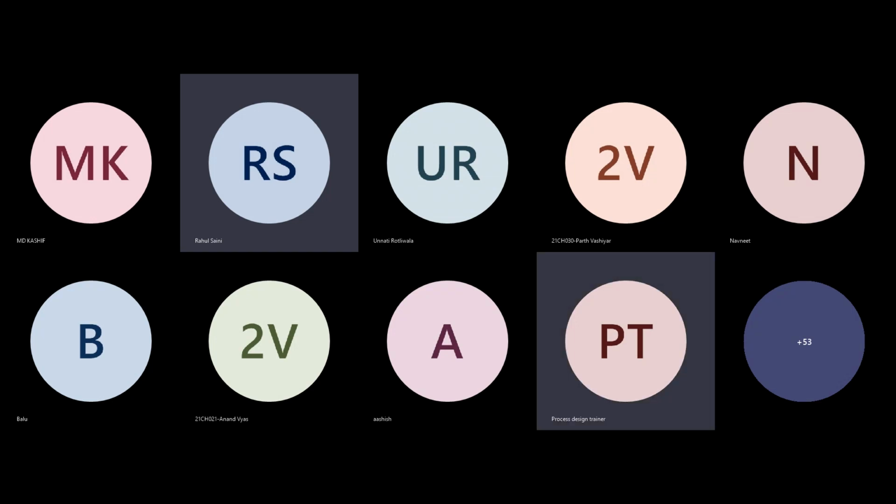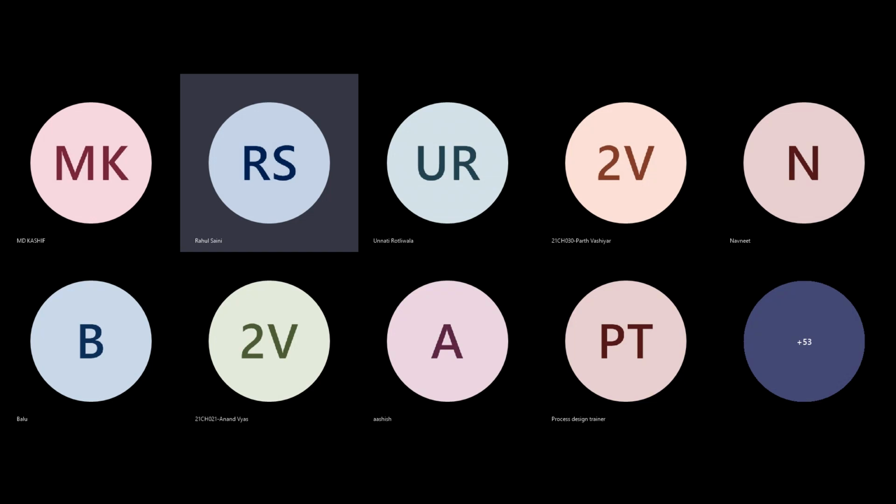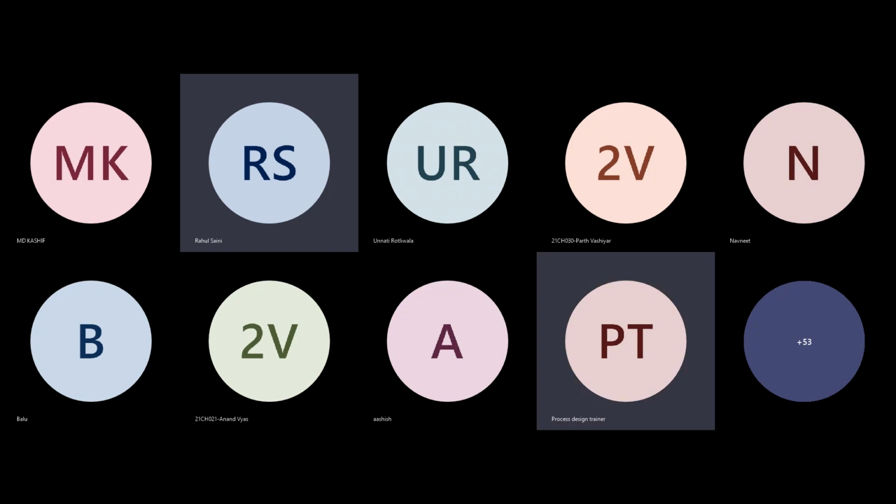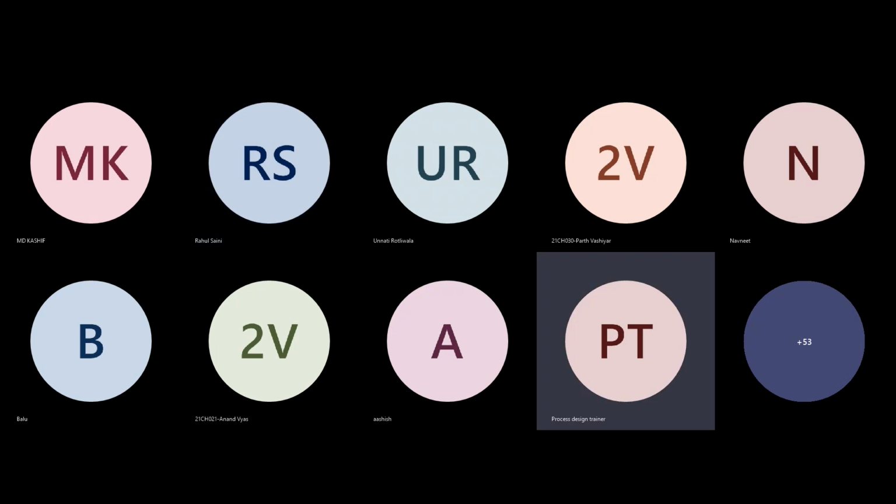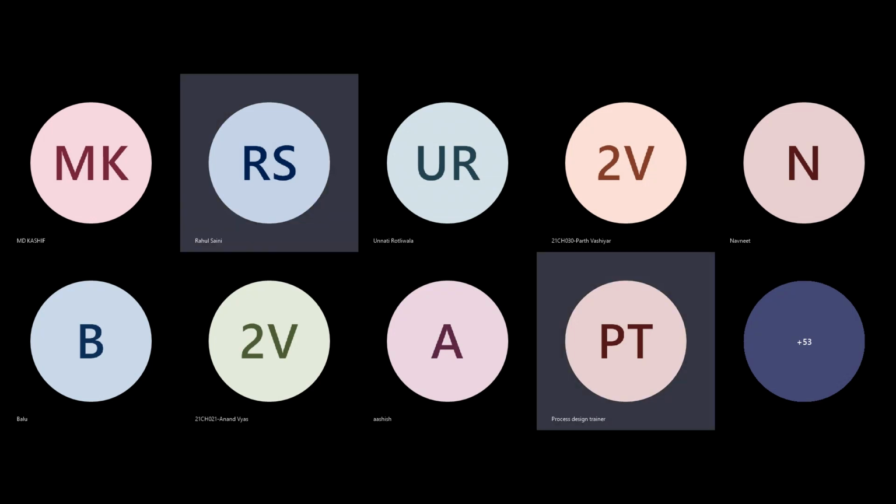We have decided we can increase the line thickness, or the schedule number. But after all, the nozzle connected to my vessel, will it be the same size, provided by the vendor itself? You can even have it reduced, whatever it is. So from a thickness point of view, you need to check. You can also have a reducer in between.